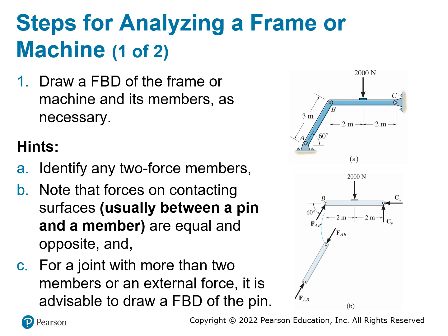However, because AB is a two-force member, the force will go along the AB direction. Do you think BC is a two-force member? And the answer is no, because you have an external force here, so BC is not going to be a two-force member. So you cannot say, oh, the force is going to be horizontal. No, it's not going to be horizontal.